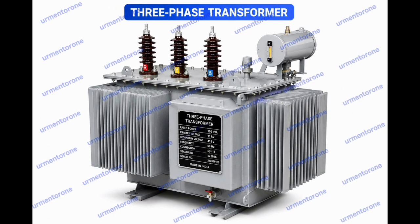Second one, three-phase transformer. A three-phase transformer operates on a three-phase AC system, which is the standard for global power generation and transmission. It can be constructed either by combining three separate single-phase transformers or by winding three sets of primary and secondary coils onto a single integrated three-leg magnetic core. It handles three distinct AC voltages that are sequential in time, separated by a phase angle of 120 degrees.